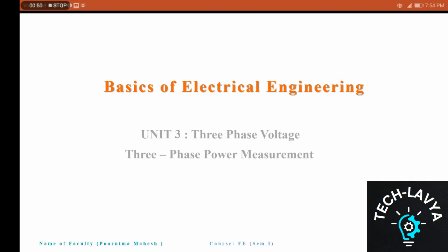But as far as an AC circuit is concerned, here you have active power, you have reactive power, then you have the total power, correct? So what is active power here? Active power is the product of RMS voltage, RMS current and the power factor. So if you measure the voltage by using a voltmeter, current by using a current meter, and simply multiply them, you won't get the power of the AC circuit because here you require the power factor also.